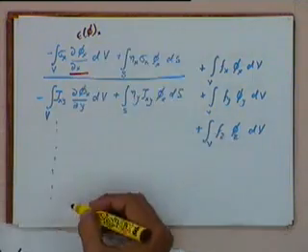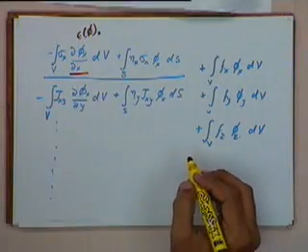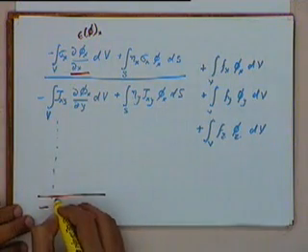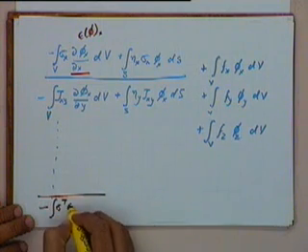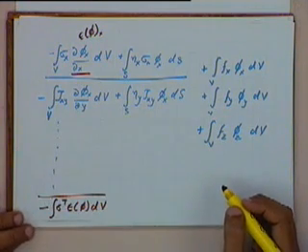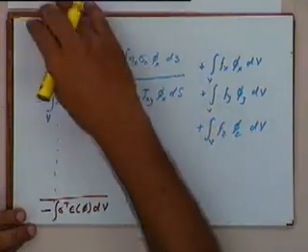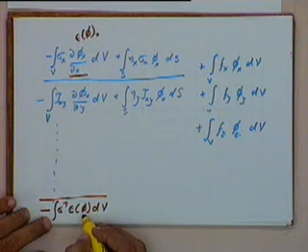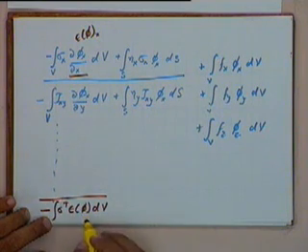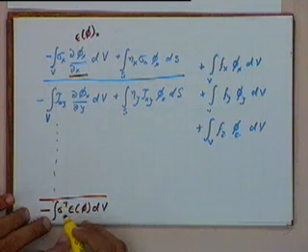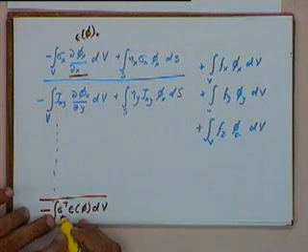Okay, so if you look at all these terms that we will have, we can collect all these terms together and we can say that this would be equal to minus of the integral of sigma transpose multiplied by epsilon of phi multiplied by dv. Now this epsilon of phi, as I said, is a strain that would be there if phi was the displacement that was given to the object, and we have already said that this displacement has to be consistent with the boundary conditions, and this sigma transpose is the actual stress in the object, the actual stress distribution in the body.